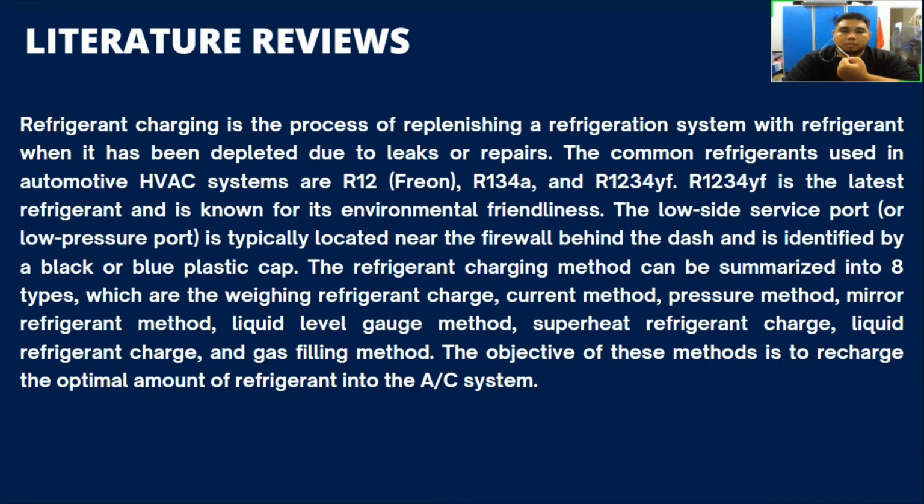For my part in this report is the literature review. As we know, the refrigerant charging process is to replenish the refrigeration system with refrigerant when it is depleted due to leaks or repair. The common refrigerants used in automotive HVAC systems are R12 Freon, R134A, and R1234YF. R1234YF is the latest refrigerant and is known for its environmental friendliness.